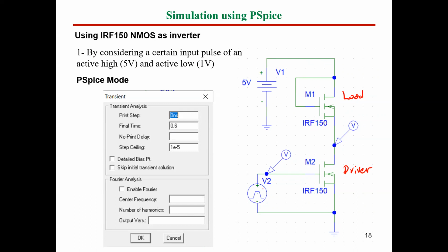So I'm going to apply here a square wave. This square wave setting can be adjusted from PSpice. So for this block, guys, you need to specify the high level volt, the low level volt, the duration of on, and the cycle duration. Okay, so these parameters have to be identified here inside this block in order to make the setting and operate this transistor.